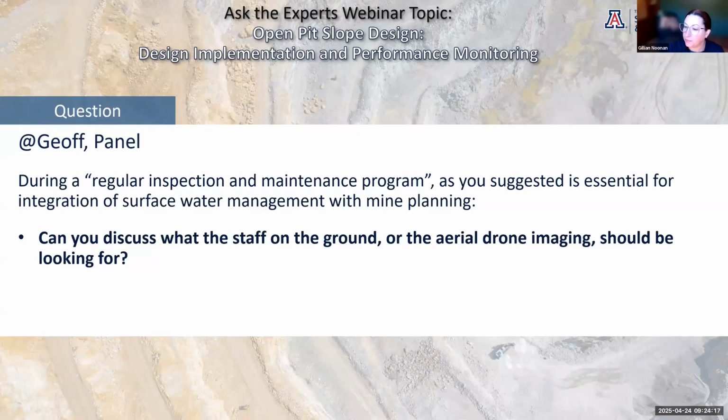Thanks, Serdar. I've got a quick comment. Go ahead, Bruce. Thanks. Exactly as Jeff has said, a lot of times in tropical areas we put in all these pit perimeter drains, they're all sitting on the plan, everything looks perfect, they have grades. But you have a couple of storms, the grades in those drains change, you have a lot of standing water, and even though it's in the drain, it's actually still sourcing into your slope.